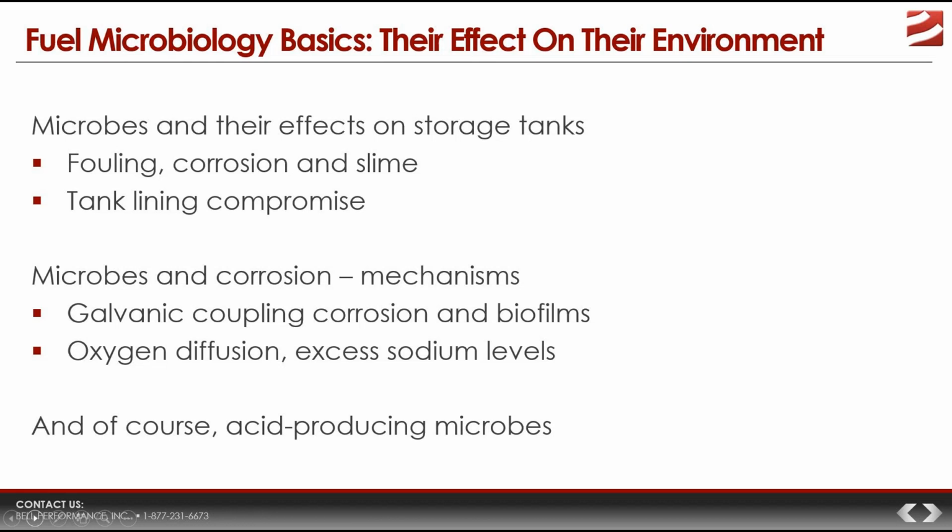Fouling would happen when microbial slime would accumulate on certain fuel system surfaces, whether it's in a filter or if it gets into or on a tank float. It can actually change the float's specific gravity, and that causes the float system to give an inaccurate fuel volume reading. Microbes can also damage tank linings.